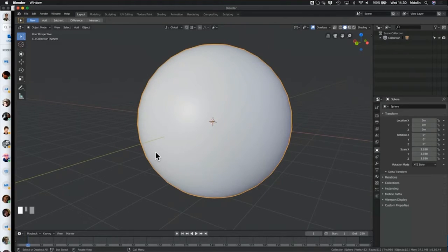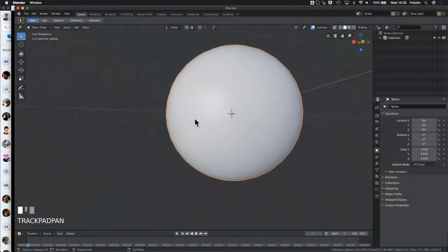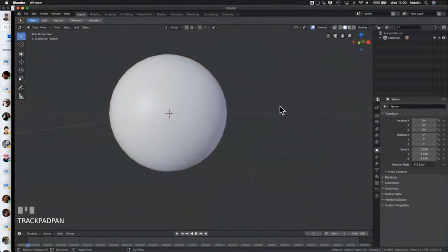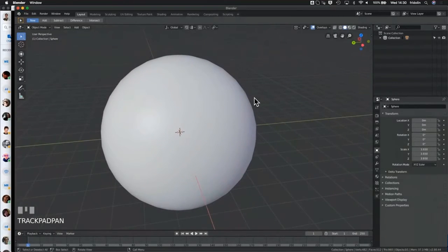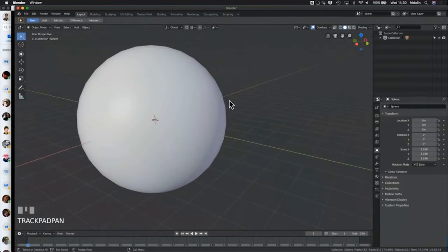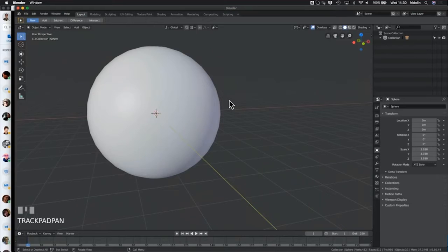So that you get this very, very smooth appearance. You can still see around the edges that it's not made from a perfectly smooth object. You can see the flatness that's used to construct it. However, it does appear in the center to be very uniform now. So they're the two different modes of shading things, flat and smooth shading. And there's a ton of other interesting approaches to shading things that we will touch on as well.